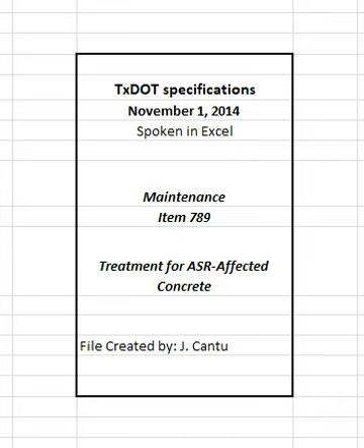2.3 Caulk. Provide a caulk meeting the requirements of DMS 8142, paintable caulk for concrete and steel. 3. Equipment. Provide equipment as listed in item 427, surface finishes for concrete, for abrasive blasting, slurry blasting, and spraying. Provide equipment suitable for application of the caulk chosen. The engineer may require demonstration of the equipment's capabilities.